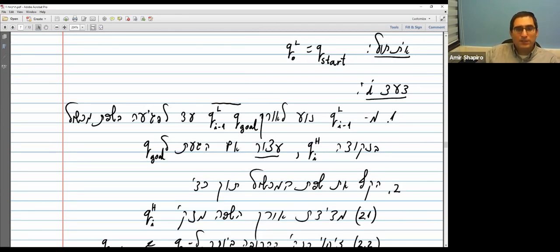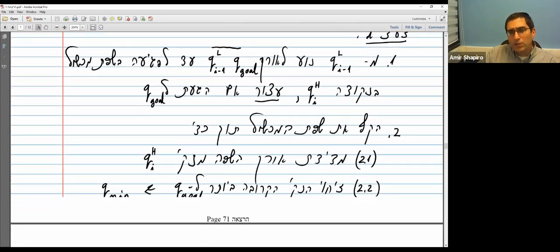If the hit point is the goal, then stop. You reach the goal. If not, you go around the obstacle, and while doing so, you measure the length that you travel along the boundary of the obstacle from the hit point up to this position.